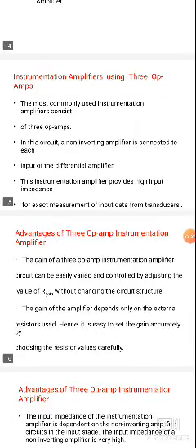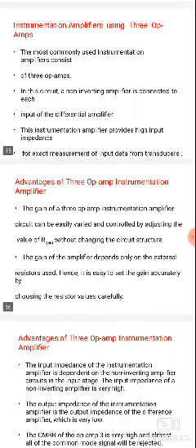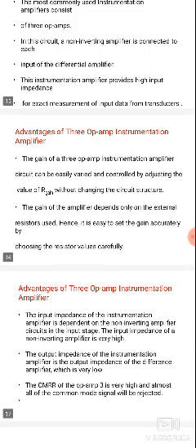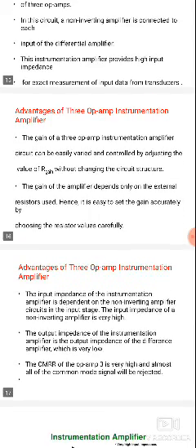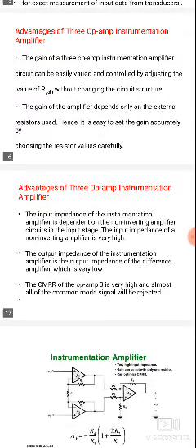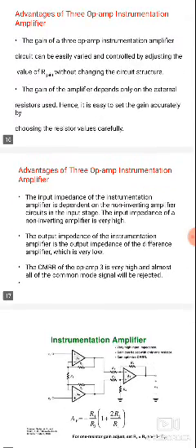Instrumentation amplifiers are used in non-inverting configuration, feeding the differential amplifier. Next, they extract data from transducers. The instrumentation amplifier gain can be adjusted by the gain resistor, meaning it depends on the gain resistor value. Then we can find the accurate value externally. It depends on the external resistor, hence it is easy to find the gain. Next, the input impedance is very high.